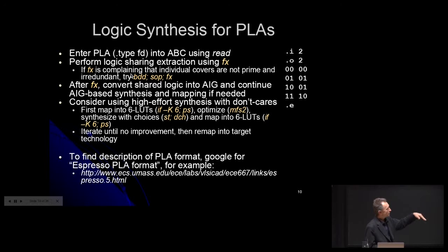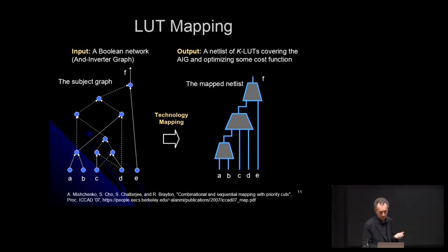and you can follow suggestions on this slide to synthesize it, and you can again do various things with it: minimize for area, minimize for delay, and eventually map it into a library or map it into lookup tables. And you can always verify it against the original specification. So that's one of the typical use cases.